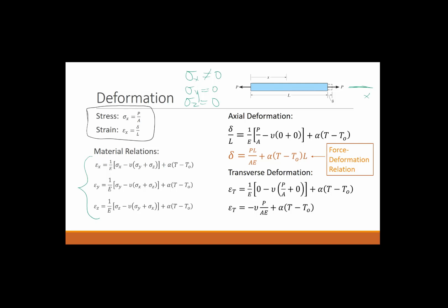So the other thing we look at is the axial deformation. So how much did it actually extend? Not just the strain, but the elongation. So if we take the strain in the x direction, because that's the way that it's elongating, and you're going to have the transverse strains in the other 2 directions, and you may be interested in those, and you can do the same thing with those, but the more interesting information is the longitudinal direction, because that's where we're seeing most of the displacement.